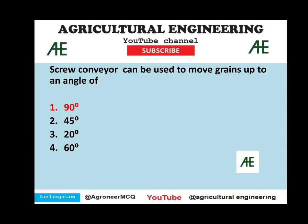While studying such type of conveyor, screw conveyor, bucket elevator, then belt conveyor, please consider some values. In a belt conveyor, we have to remember how much the trough angle is, whatever values are related to this conveyor and conveyor system, you should have thorough knowledge about that. So screw conveyor can be used to move grains up to an angle of 90 degree.